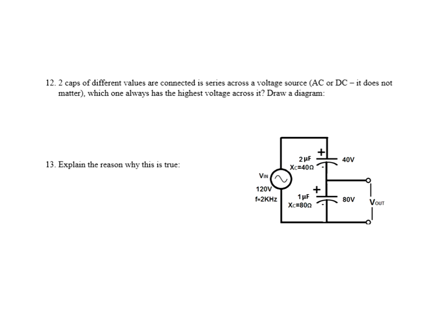Now, here's an interesting aspect about capacitors in series. Whether it's DC or whether it's AC, what we find is that the capacitor that has the smallest value of farads will always have the larger voltage. The reason behind that is that a larger capacitor has what appears to be a lower opposition to the actual flow of DC or AC through it. And therefore, the smaller cap will have more opposition and will gather more voltage.